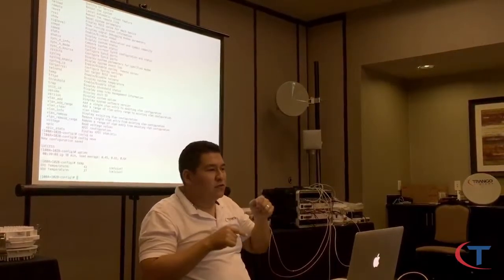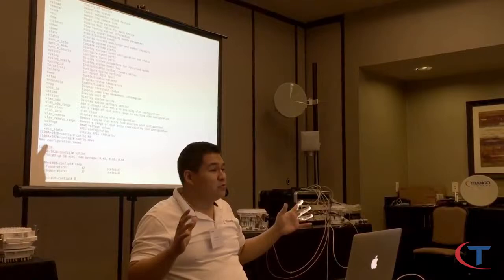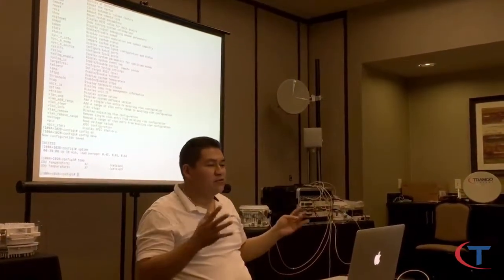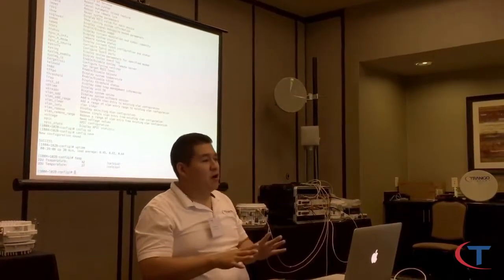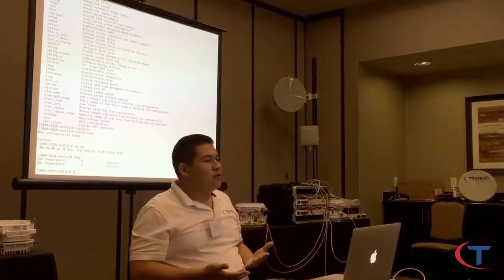The link from Black to Woodson unlocked suddenly. I scrambled to look at my ODUs and my IDUs. I didn't see a problem. I could actually get to the ODUs, turn it back on, ODU power on, and it worked. But I didn't know what the problem was. I was wondering, why did it unlock on me? I started a little more troubleshooting.